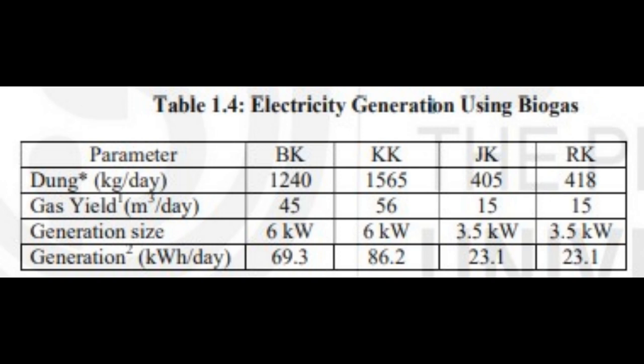The difference between the demand and the combined generation by biomass and biogas represents the demand, which has to be met by PV. 3. Steps 1 and 2 of case 1 are repeated. 4. The generation required from biomass and biogas are then evaluated, as discussed in step 2 of case 2 and case 3. Excess biogas is passed for cooking. 5. Battery size is evaluated as discussed in step 4 of case 3. 6. Total life cycle cost of the system is evaluated.